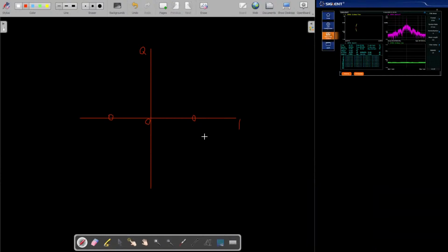So there is no something like a long stream of ones or zeros. So for a random stream of zeros and ones, for BPSK, there should be no DC component. And in our case, we of course see that component, which is a small hint on what's going on and what's wrong with the symbol stream that we send. Actually, not the symbol stream, but the phase words. So 1000 and some negative value, F600. So something is wrong with those values. That's the hint that we get from the DC peak.